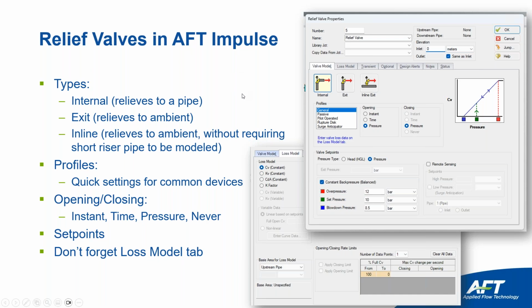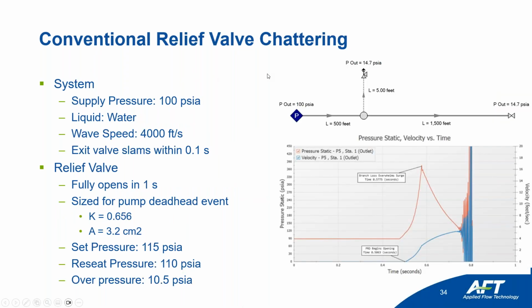Because these aren't as well studied within the standards, usually it's just advertised that you should go out of your way to avoid them if you can. There's not as much in the way of papers that go into more detail on these types of things. So for the paper that we wrote, we were more interested in determining how relief valves react to surge and these higher overpressures. And one of the common cases that you hear with relief valves for an overpressure that it wasn't designed for is a chattering case.